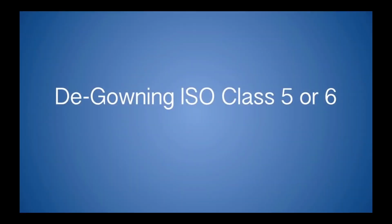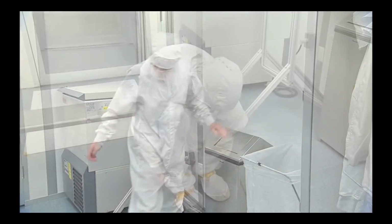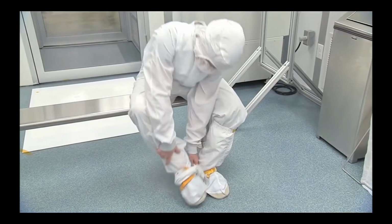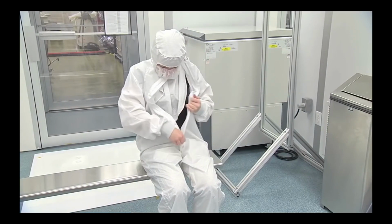The process for an ISO class 5 or 6 cleanroom is similar, but it will be different. Once again, take everything off in the reverse order that you have to enter. Remove gloves completely and place them in the trash. Remove each cleanroom boot. Unzip the coveralls, remove the sleeves from your arms, and sit on the cleanroom bench.